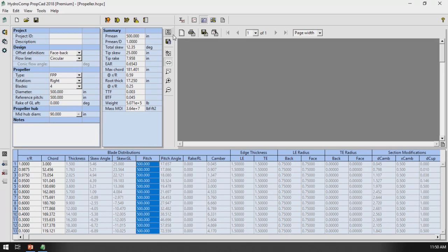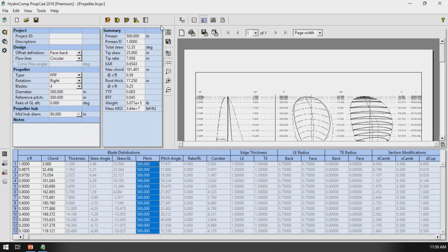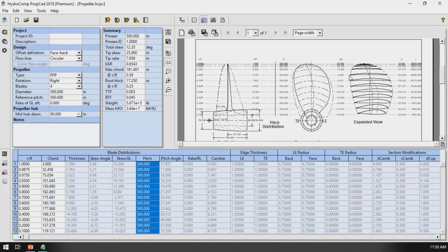The third way I'd recommend is to actually take drawings and overlay the drawings on top of each other using the DXF export, or using a projector table with some light behind it and taking 2 printouts and laying them on top of each other. And you can manually check how well the outline matches, how well the section shape matches, etc.